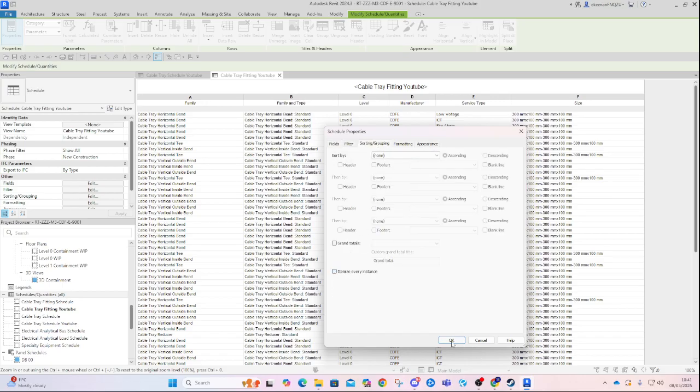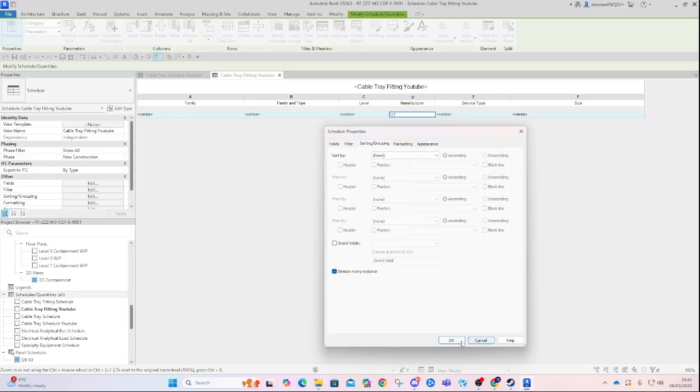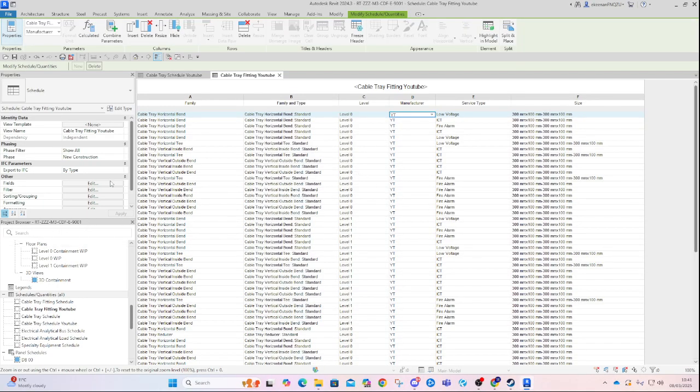Yeah, untick itemize for every instance. We hit manufacturer and we just hit YT. Hit OK. And then you can just go here. So you can do it either way. I usually just go here and tab across, but whichever way suits you. And that's it. That's our schedule and quantities there.